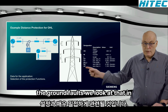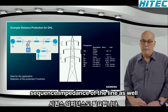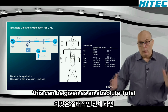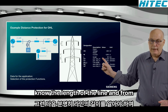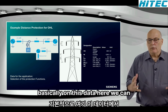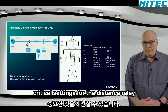For the ground faults, we'll look at that in more detail later on. You need the zero sequence impedance of the line as well. This can be given as an absolute total line impedance, or as in this case, given as a per kilometer impedance. And then you obviously need to know the length of the line. And basically from this data here, we can really calculate most of the critical settings for the distance relay.